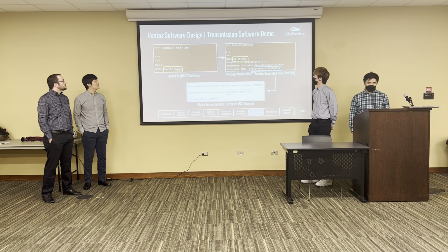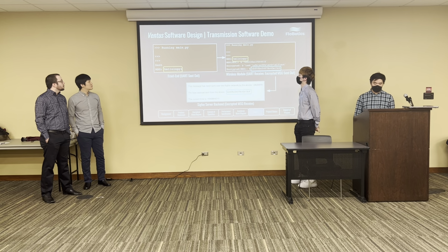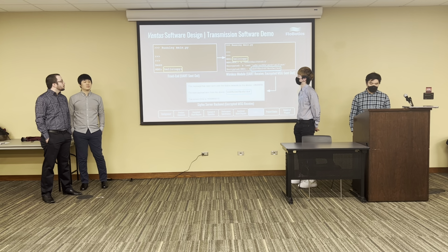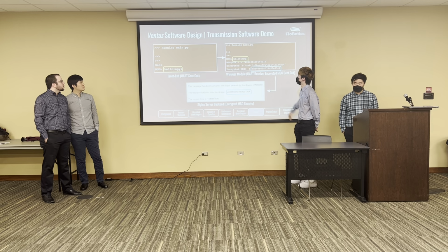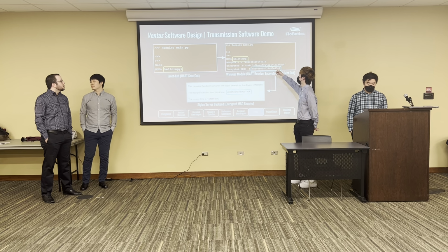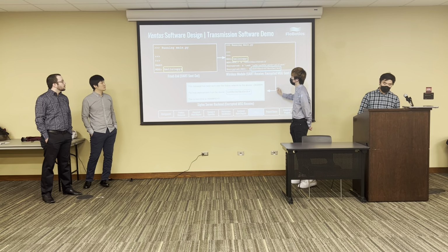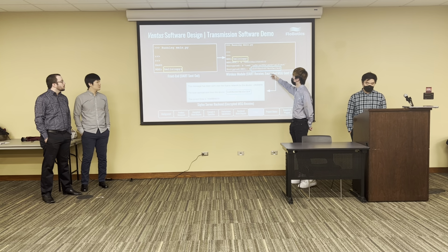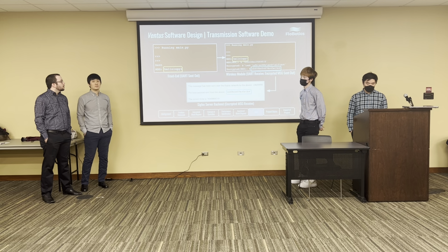And here is our quick simulation. As you can see, this side should be our front end. We're trying to send out some simulation bytes through the UARTs. We're sending the "hello LoRa Pi 1" to the LoRa Pi module, which is our wireless module. We receive the package, then we encrypt our data as this, and we send it to the cloud server, and this is the callback email we receive. As you can see, the two blue boxes have the same data, which is the encrypted data we received overall.